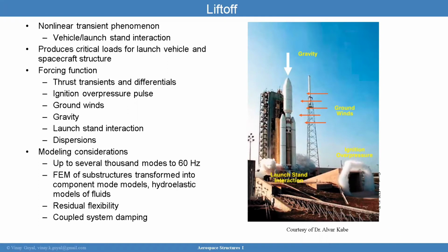Other things I want to point out, there are stresses due to direct acoustic impingement, and that needs to be looked at. You also have the issue of acoustic excitation, and it is important to understand that the space vehicle acoustics test does not induce the total load that the primary and secondary structures will see. Okay, and so these loads, you can apply them in a static strength test. That could be one way. The static test load should be the combined low frequency transient values obtained in the liftoff simulation.